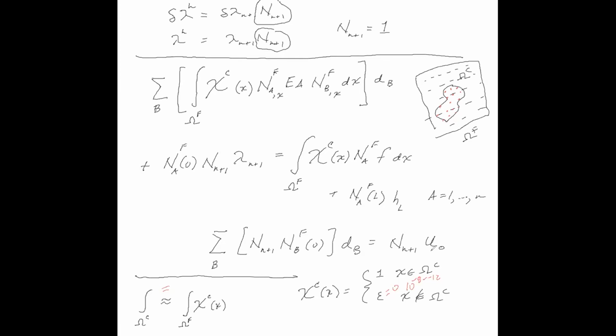Sure, but in practice, we're rarely even in that asymptotic regime, right? So in practice, if you were to use linear basis functions, you would engender quite a bit of error along these boundaries. But what we find with splines is that error is far superior to what you would achieve even with body fitted traditional FEA. And in fact, all of the boundary quantities converge optimally at higher order rates.